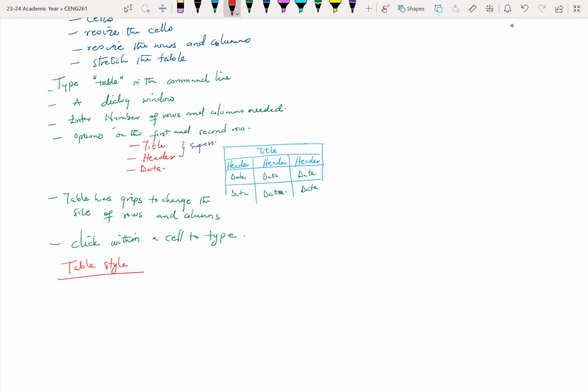You don't want to come back each time you want to draft and set your paper limits, your dimension style, your units, your table style, your text style, your multi-line style, and all of that. That takes forever. And one of the key things about AutoCAD has to do with its efficiency. So usually you would prefer to spend time creating one file which has how you want all your data to look.